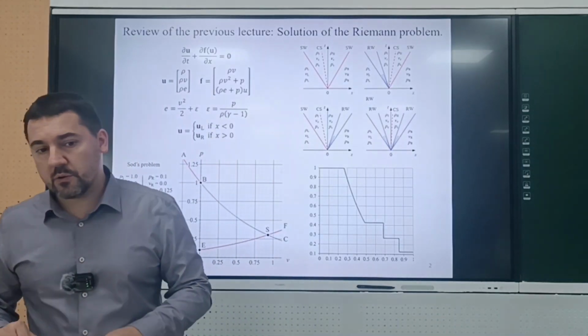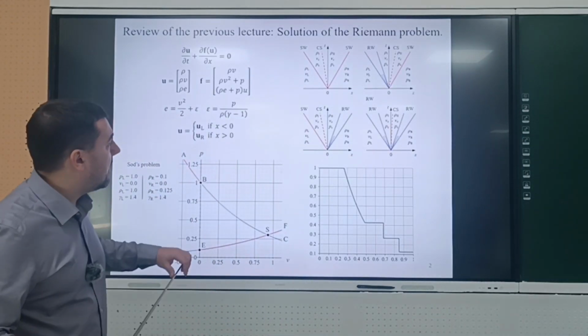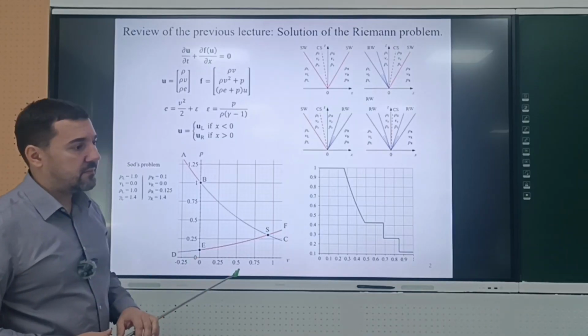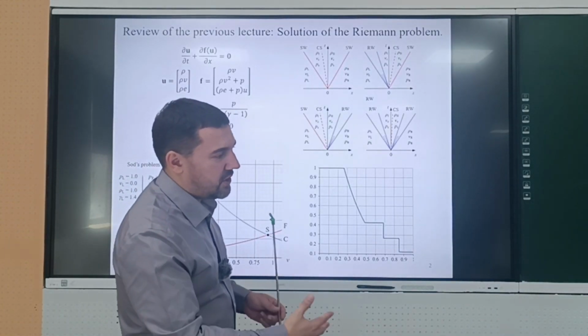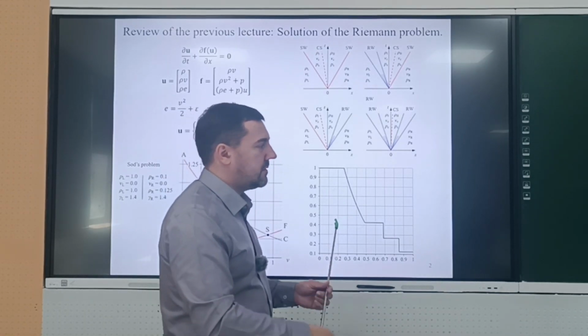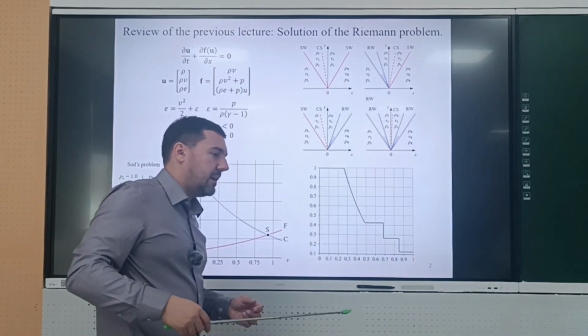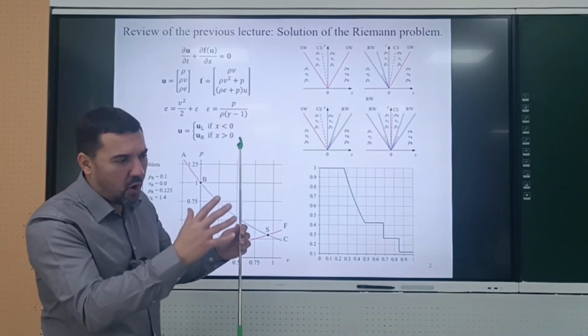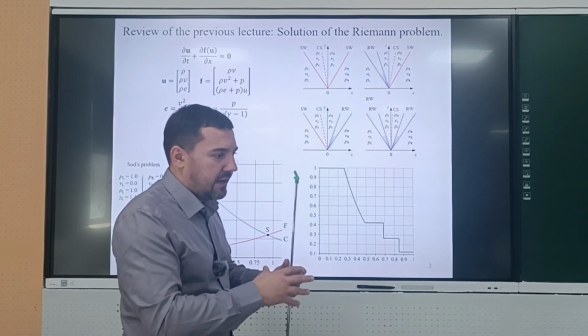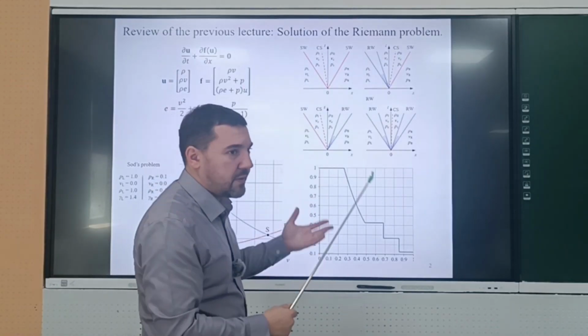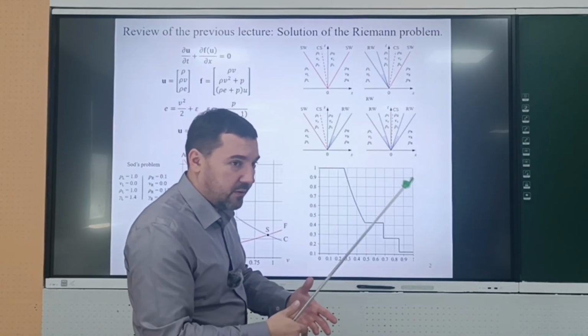And if you need to use a more complex equation of state, it is known how to write the Godunov method for the so-called Stiffened gas equation of state. But it's actually the most general equation of state that can be used to write the Godunov method. It means that if you have some complex equation of state, you need to locally approximate it using formulas for which the Godunov method is known, and then locally apply the Godunov method.